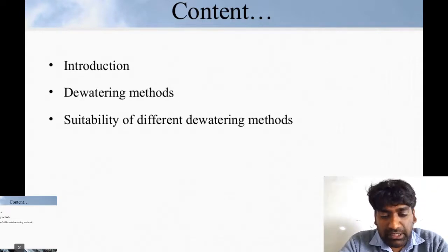If I talk about vertical stresses and stress distribution under loaded area, I have discussed Boussinesq's theory and Westergaard theory for concentrated, circular and rectangular loads, pressure distribution diagrams, contact pressure and Newmark's chart. In bearing capacity, I have discussed definitions like ultimate, net and safe bearing capacity, allowable bearing pressure, Terzaghi and Brinch Hansen bearing capacity factors, their assumptions and limitations, bearing capacity of footing subjected to eccentric loading, effect of groundwater table on bearing capacity, layered soil, field methods of evaluation of bearing capacity and their limitations, plate load test, standard penetration test and cone penetration test.